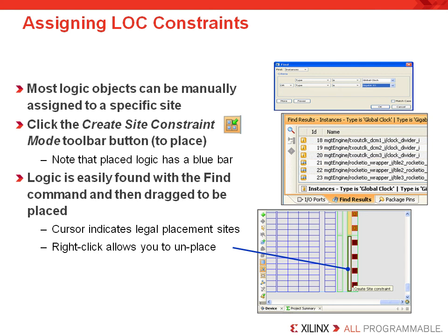When you place instances into sites, PlanAhead adds instance location constraints to exported UCF files for ISE. The assigned locations are marked as fixed and locked during subsequent ISE attempts. Most logic objects can be manually assigned to a specific site.